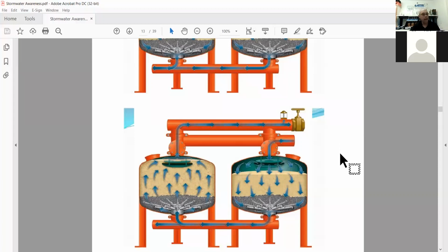All right, and then I had an additional question. It was, how is pH corrected with stormwater? It's using three methods. One, we'll sparge gas into the waste stream through an injection quill and a static mixer. We can add pH correction chemical to the tanks or ponds by hand, or we can add chemical injection into a static mixer. Those are the three methods to correct pH.